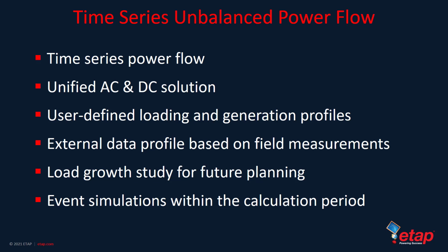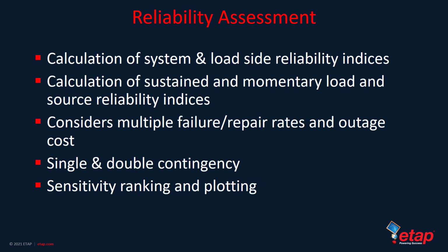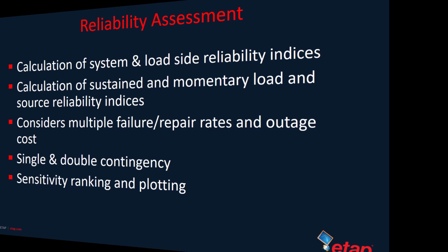It is the time domain unbalanced power flow, or time series distribution load flow simulation, that is used for the purpose of varying load and generation in the system and solving the steady state power flow in the system as a function of time. The time series unbalanced power flow analysis module includes key features such as single year load growth analysis, multiple year load growth analysis, and also solar and wind farm annual yield and losses estimation. We're going to quickly go over a demonstration of this.